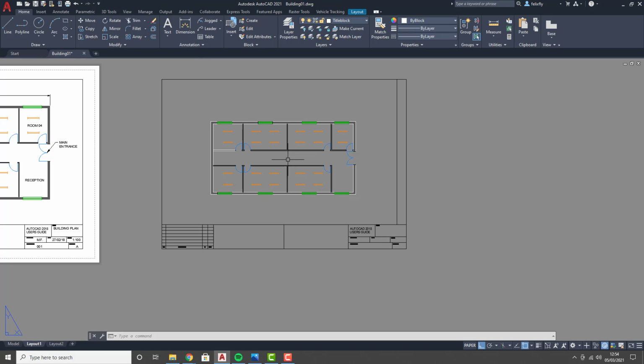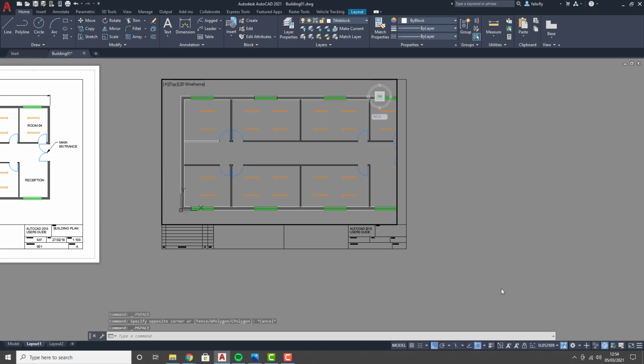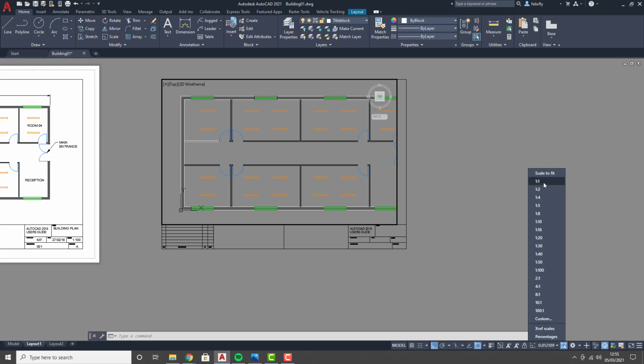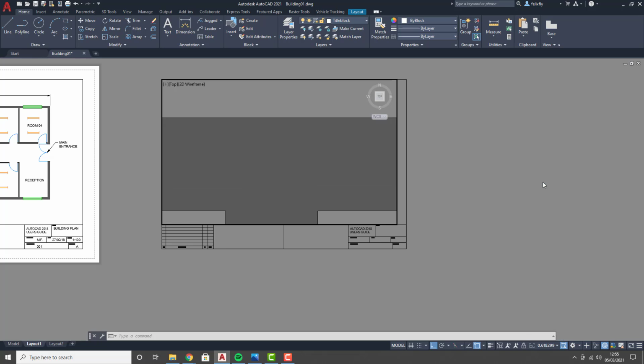And we can do that easily in CAD. So we can double click in our window, and instead of using the zoom command, if we look down here, we have the standard scales set up. So if we wanted to show its actual size, that would be 1 to 1. And if I just pan it a bit so we can actually see something. So if I set this at 1 to 1, that is actual size.